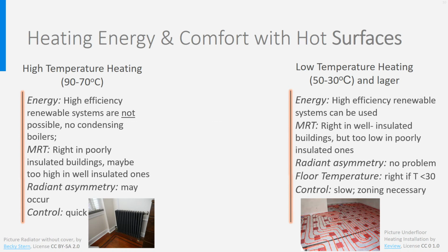If the building is not well insulated, the floor or wall heating will not be able to compensate for the cold walls and windows, leading to a too low MRT. So, even if the needed heat as calculated with the heat balance at the beginning of the lecture is supplied, residents may feel very uncomfortable because of the too low MRT. That is why it is strongly recommended to apply low temperature heating only in well-insulated buildings.